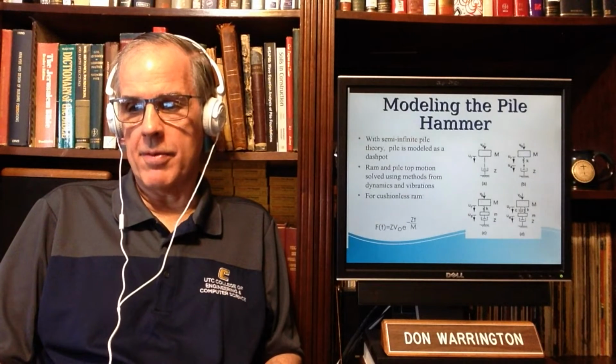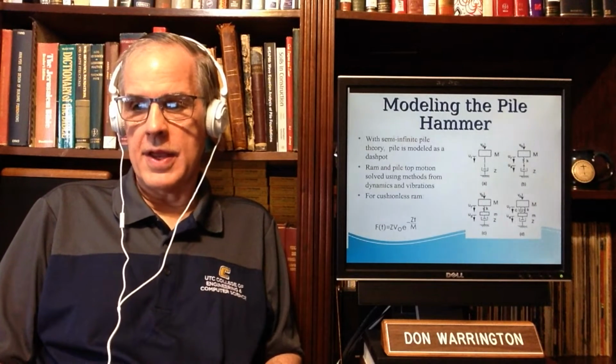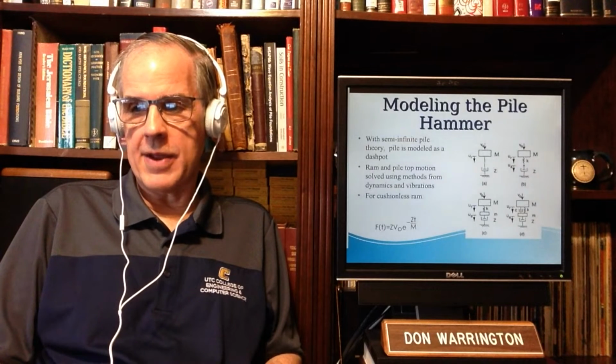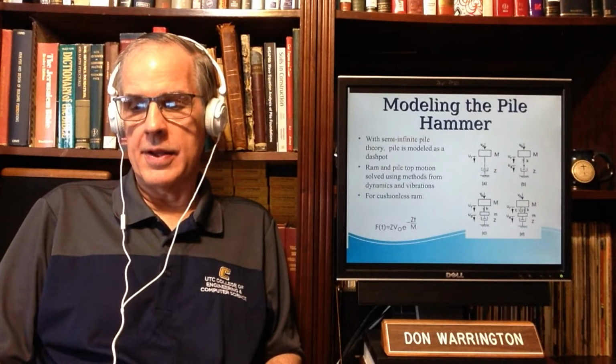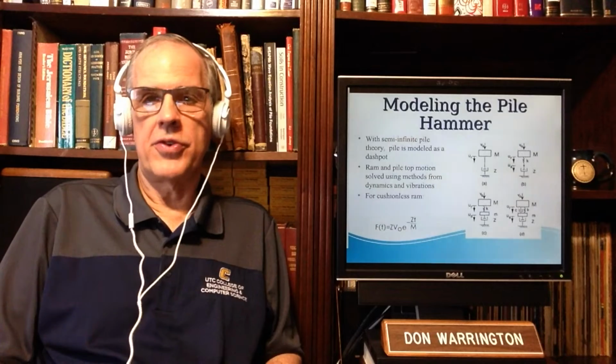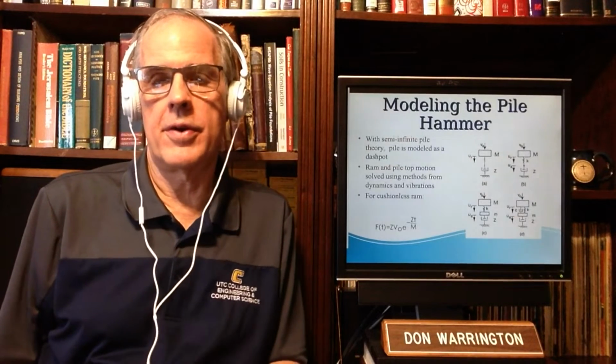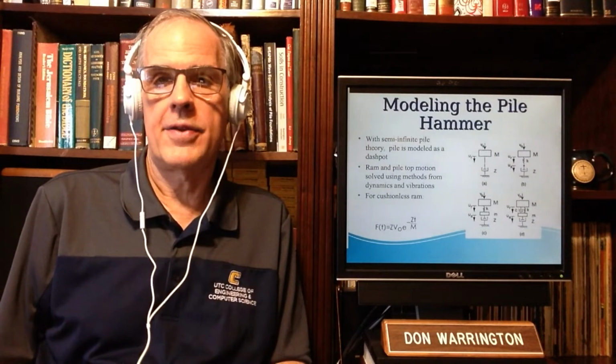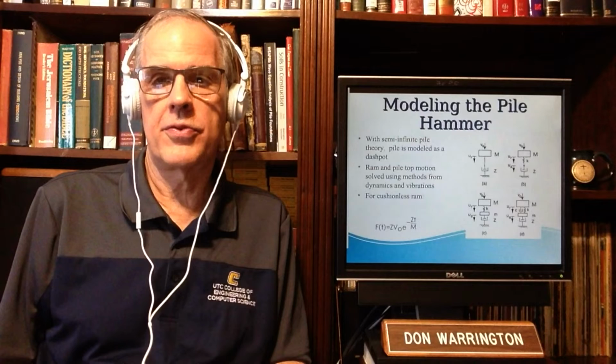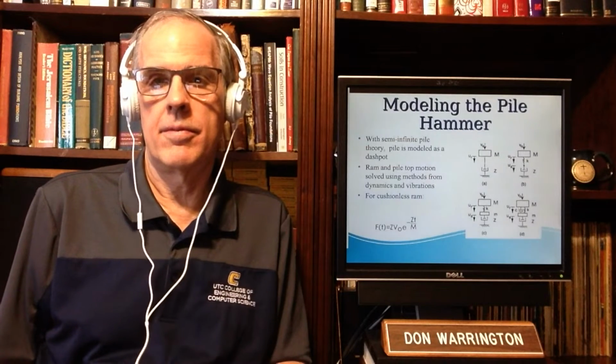The Z is at the bottom of all four of those. What's different is that the K can be modeled either without a cap, or there's also usually a driving accessory. I talked about driving accessories a little in some of my earlier lectures. It has mass. It modulates the stress wave going into the pile.